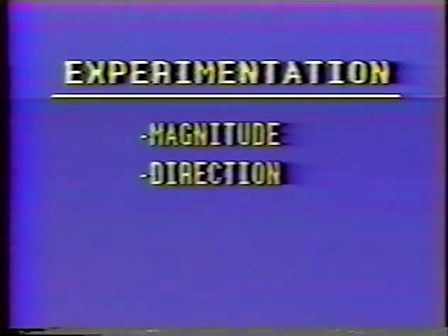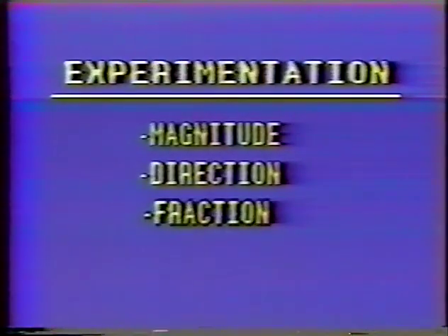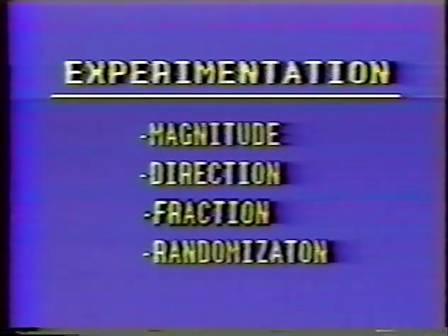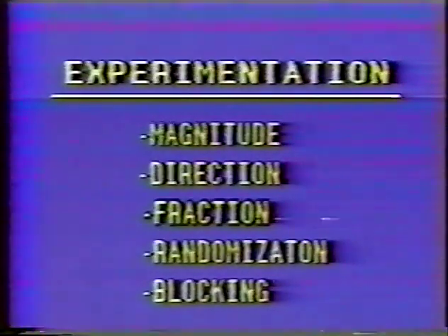The fundamental difference between testing haphazardly to hit upon an attractive result and experimentation, which reveals the magnitude and direction of variable effect. The power of using only a fraction of a full factorial design to study many variables in relatively few tests. The importance of randomization to counteract unknown sources of nuisance variabilities. Blocking as a tool to eliminate known nuisance variation. And if the experiment has been properly designed, the analysis of the data is straightforward and easy to perform.